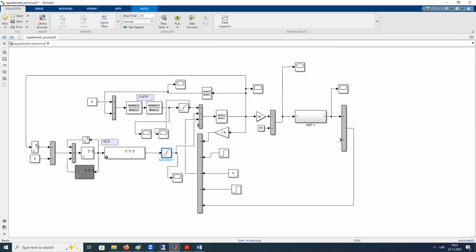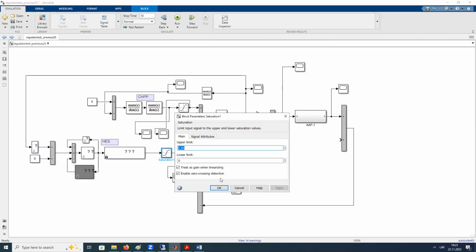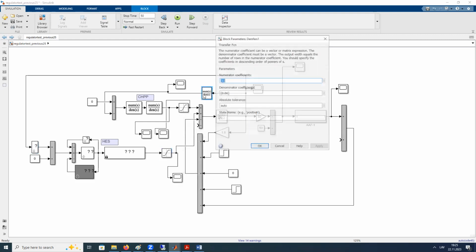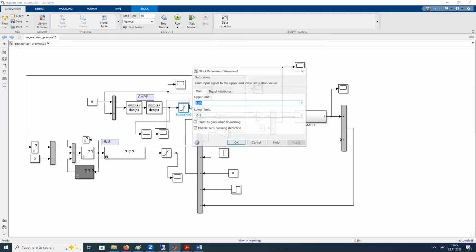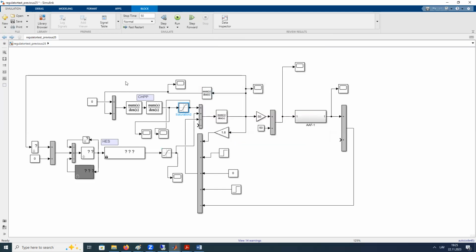So in this case, we have a regulator, the statism, and a power limitation. In this way, based on the static curve, we are setting the power reaction to the frequency deviation at each time step, and here we are adding a limit of power. So this scheme is more true, because the previous scheme was more simple.